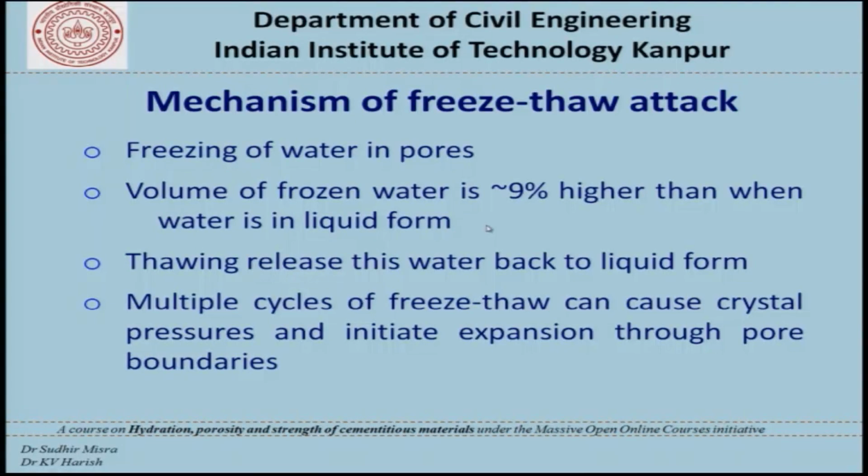So the pores try to expand and the concrete remains like that for some period, and once the temperature increases, it goes to the thawing stage, and the frozen water comes back to the liquid form, and now the volume decreases, and again the concrete may be subjected to freezing.